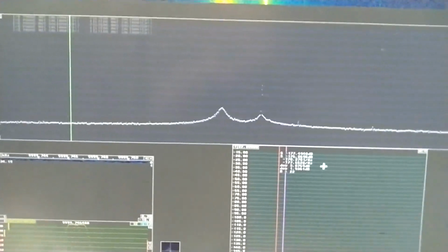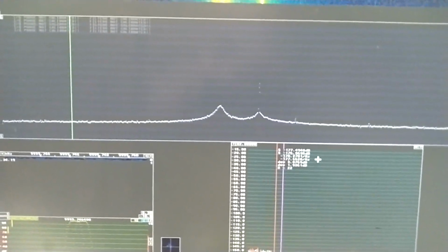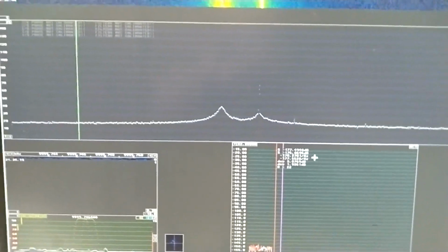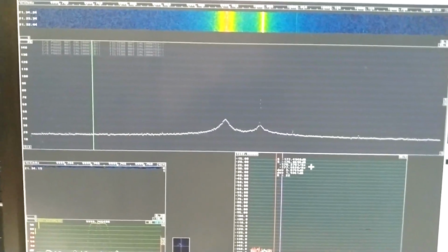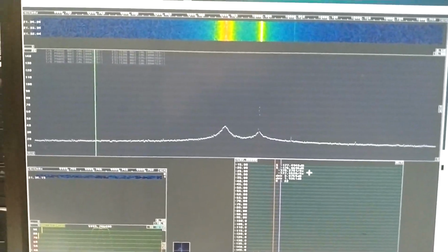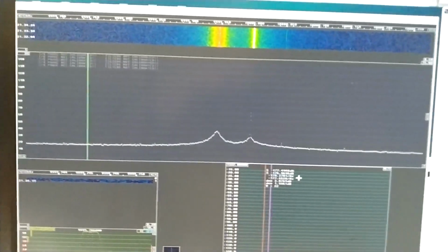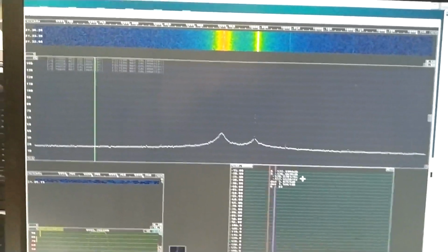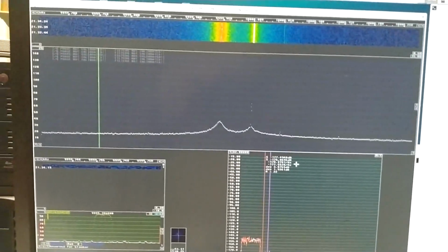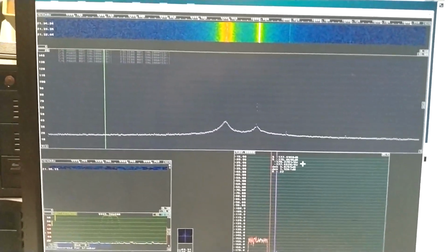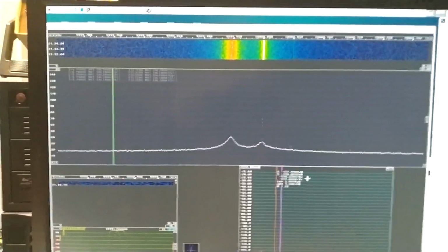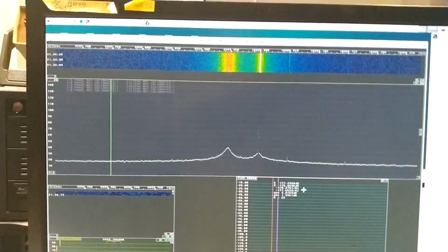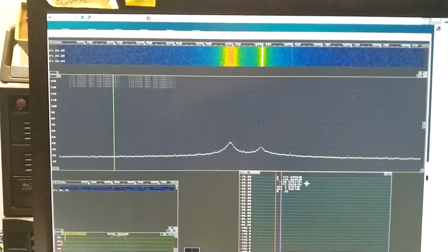And that comes as minus 178. But this is amplitude noise plus phase noise, so the phase noise should be minus 181 if there is no sideband noise generated in the system, just only the amplifier white noise.